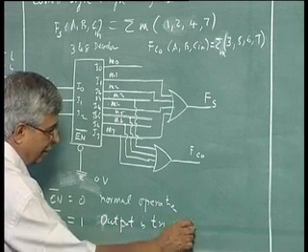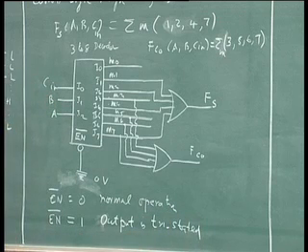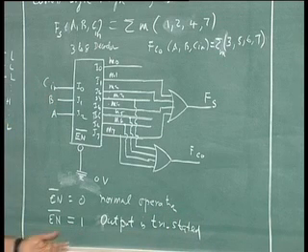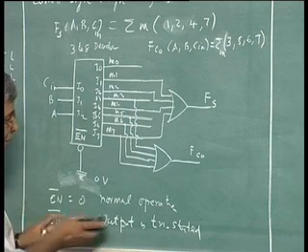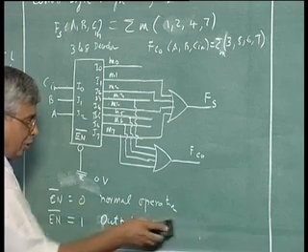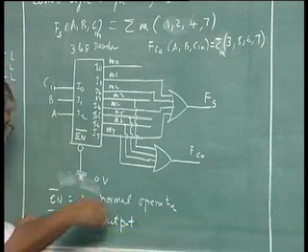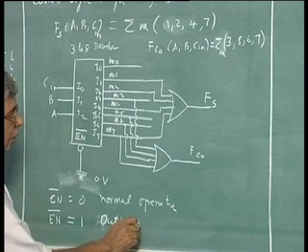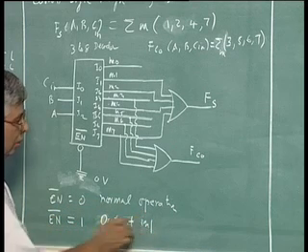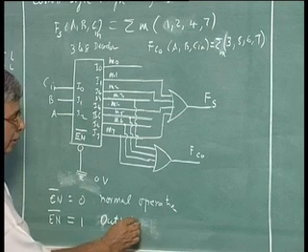What is tri-stated? We will see. It is the same as electrically not being output, or I can say output impedance is very high, output high impedance. You do not like this term now, since I have not explained it to you, I will do it in a minute. Output impedance high, output high impedance state.